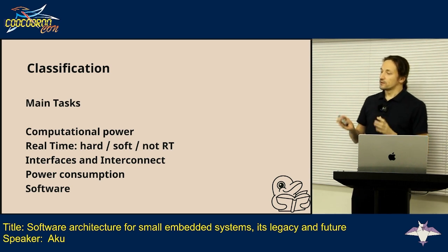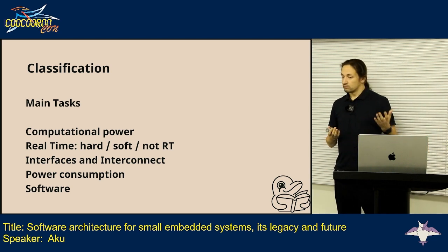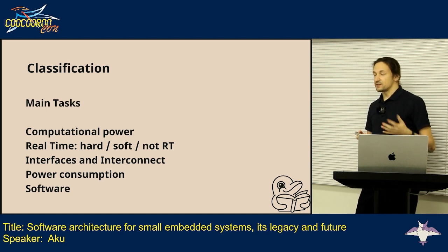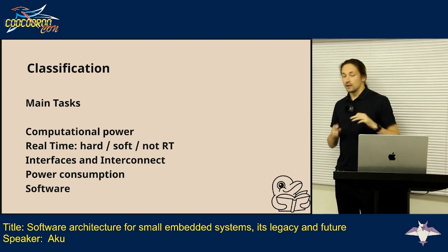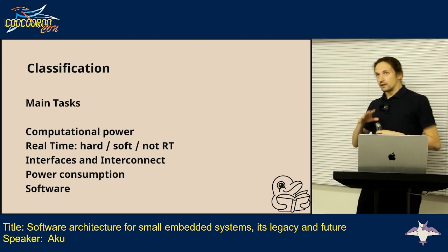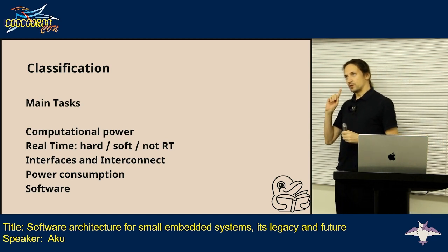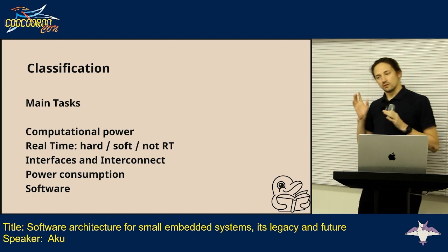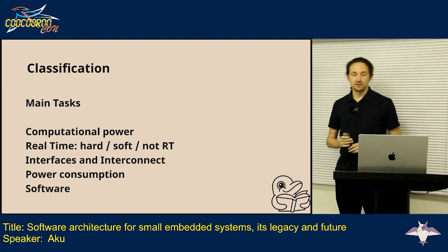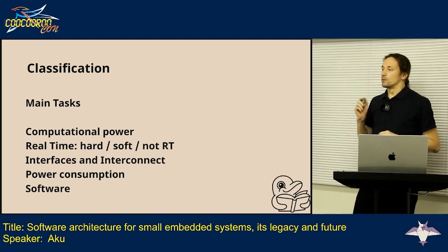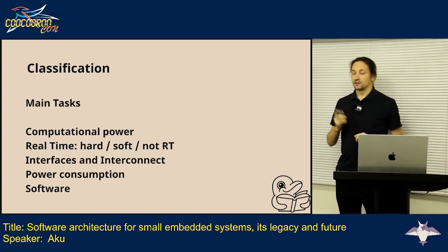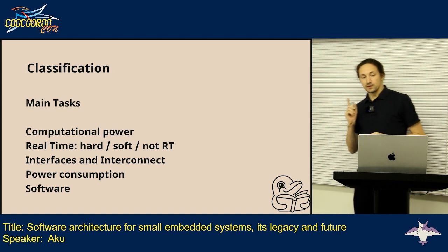Then we have faster buses, like parallel buses, serial buses, SPI, I2C, LVDS, and a lot of different things. And all those small things you have to keep in account when you start to design software for all those things, because some of them actually require your software to react on those receive or transmit events in a predictable fashion, and that's where real-time becomes important.